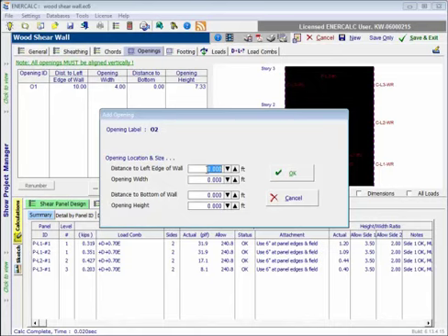We'll leave those to the section that's dedicated to that topic in the user's manual, but please do take a look at those. There's quite a bit of intelligence built into the module itself that will flag openings that are not allowed. It'll use some warning text here on the screen, and as we enter some values here to start to define this next door, we may actually see some of that warning text pop up because it's got partial information, so it's going to think that we either have overlapping openings, or we have openings that cross a floor level or that hang partially outside of the wall, and so on and so forth. But just be aware that there are limitations.